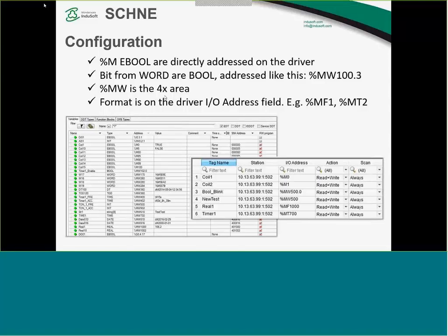But here we are showing that on Unity Pro, on the type, you have different formats. So let's say here the %MW1000 is of type real. On Web Studio, what we do is we configure it as %MF1000. That's how we communicate with this variable here. But this is only if we are addressing the variables directly. Using tag integration, you don't have to do that.